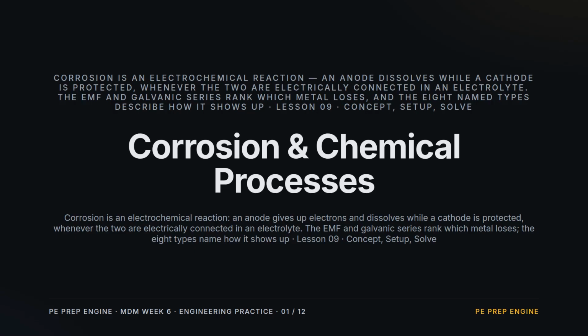Week 6, Lesson 9, Corrosion and Chemical Processes. Corrosion is an electrochemical reaction. One metal, the anode, gives up electrons and dissolves. The other, the cathode, is protected, but only when the two are electrically connected in an electrolyte. Take away any one of those three and corrosion stops.